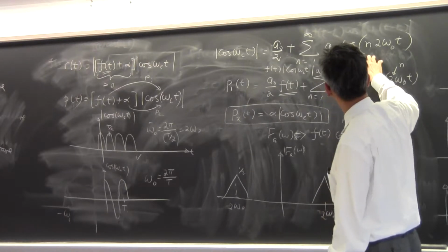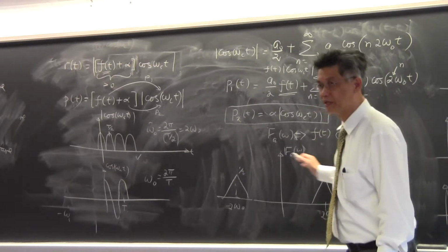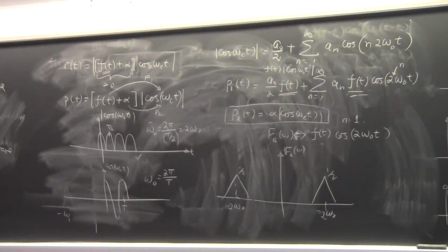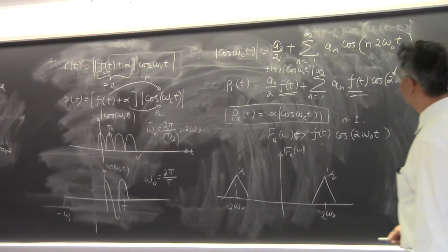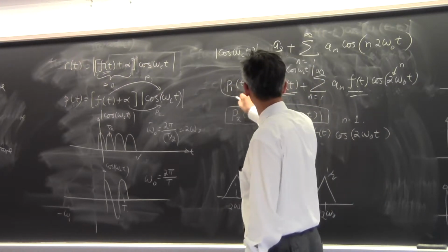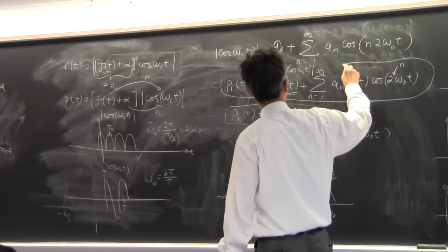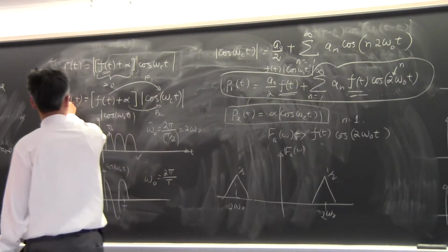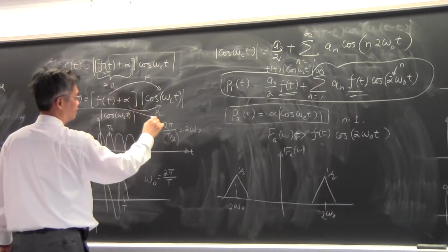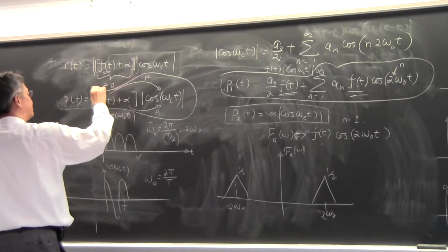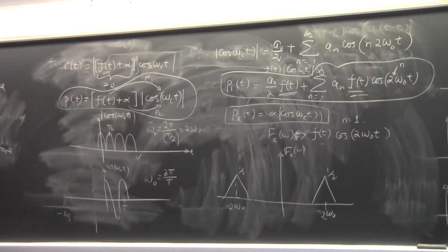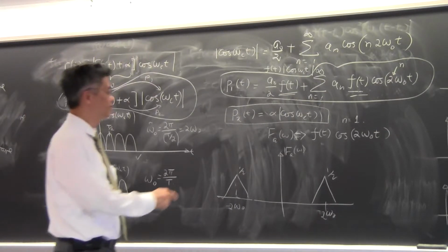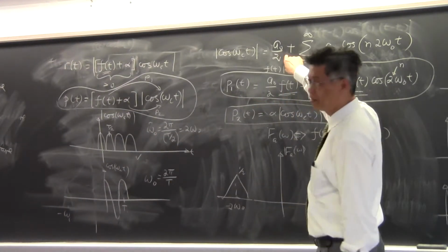Okay? And the others are just higher Fourier harmonics that go outside the low frequency band. So if I take this signal p1 and p2, sum them together, p1 is this signal, p2 is that signal, and essentially if I take my p(t), pass it through a low pass filter, what do I pick up? I pick up this term plus alpha times that term.